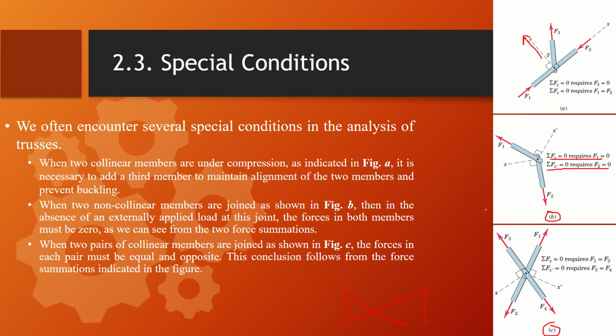However, when the braces are flexible, meaning these interconnecting braces are cables, they are incapable of holding any compressive loading. As I have mentioned earlier, the only force they can handle is tension, and the slack members can be disregarded and we can discard them.